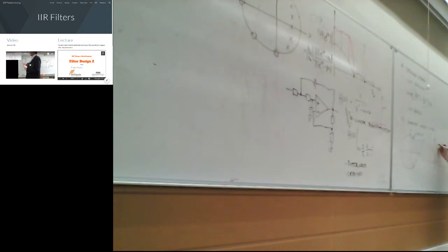So after this, you get the amplitude response of this filter is much better in sense of filtering properties. So it has almost flat passband, controllable bandwidth, and controllable notch frequency. One more detail. Okay, we expand this part or that part there. Okay, let's put this one.